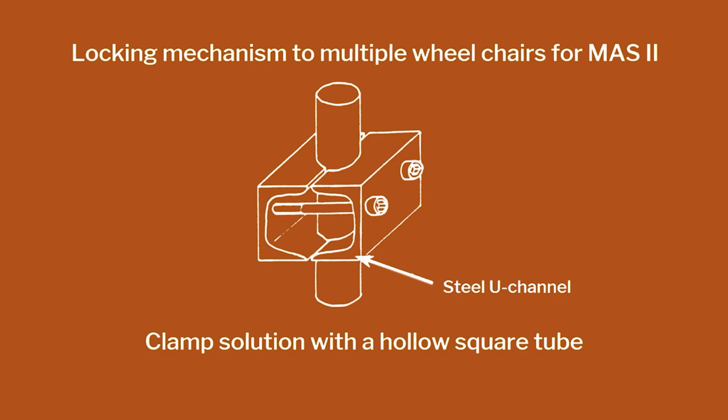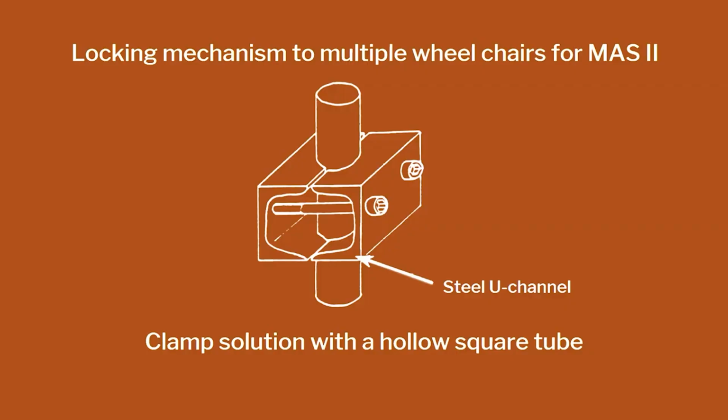Finally, that's the design. You have one channel section, and that can come from the same material, right? So I can take a single stock and keep cutting and then turn it around, make the cut, and I'm ready. And then you connect with 2 screws, so your number of parts has dramatically come down, your weight has come down, your reliability and robustness has gone up. And that's the final design.